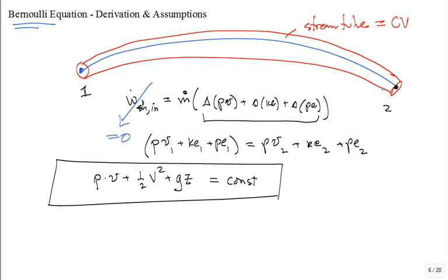Does it look familiar to you? Can you follow the derivation? It's really a subset of the energy conservation statement. It's a mechanical energy. So let's go back and review some of the assumptions that were here. Well, what about steady? Isn't it steady state? Do we have anything about the fluid being incompressible? You can modify it for transient. We're not doing that. Let's leave it at the generic Bernoulli's equation.